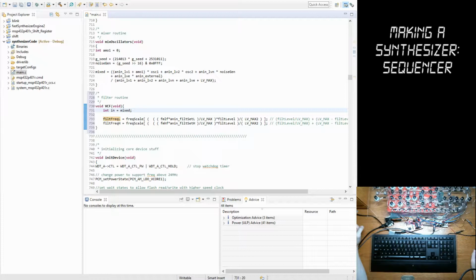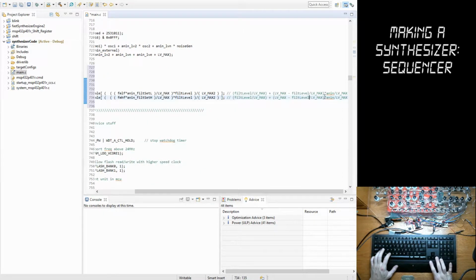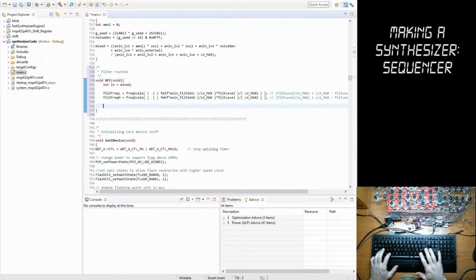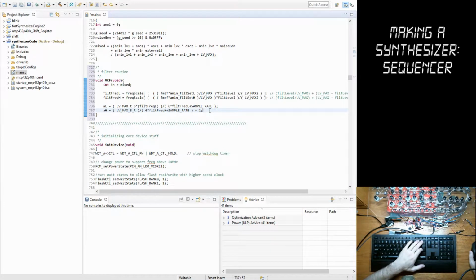Alright, there's a certain kind of algorithm that I'm going to be using to perform the filtering, and it requires, instead of using the actual filter, kind of a scaled form of the filter based on our sample rate that we're pushing out to the DAC. And this just basically allows us to work in this discrete domain. There's a couple different ways that you can do filtering. In this case, I'm using this sort of algorithm that I'm about to show you. As far as I could tell, it uses the least amount of calculations of the other methods that I could find, and it works pretty well.